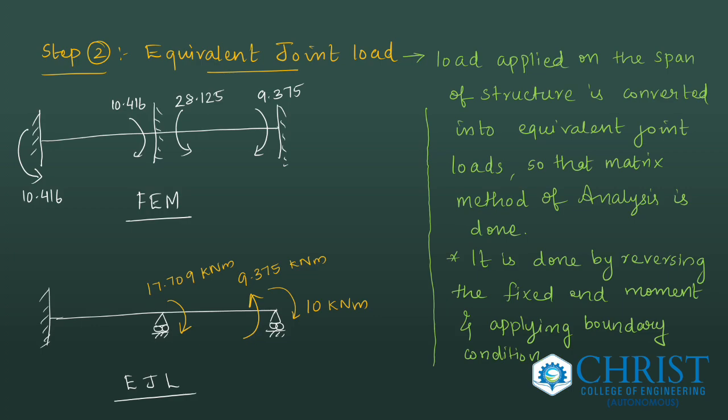So that is nothing but low applied load in terms of joint loads, right? So we are converting the fixed end moments into equivalent joint load acting as an applied load on the joints.